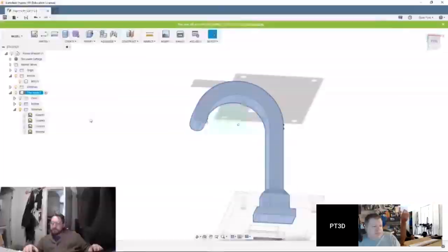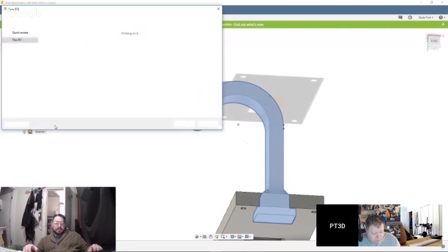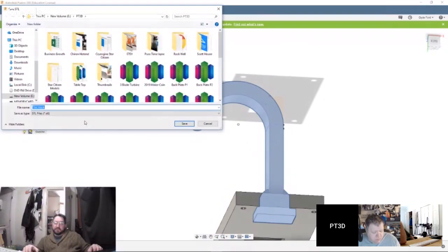Well, you can do blown in. Blown in's reasonably cheap, and it works beautifully. You only have to go back in about 5 years, and I always cut like 4 inches of sheetrock and re-stuff on top. Well, we've cut our propane fuel usage in half just doing the attic. Oh yeah, 90% of people don't realize you can leave your walls uninsulated if you insulate your ceiling. That's like half of your heat loss right up through the roof. So that's been nice.